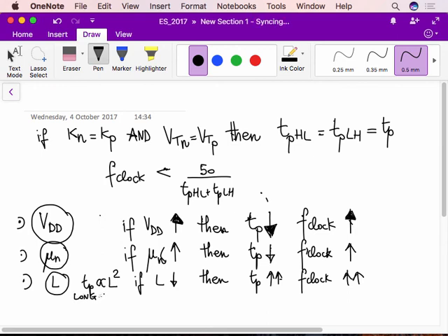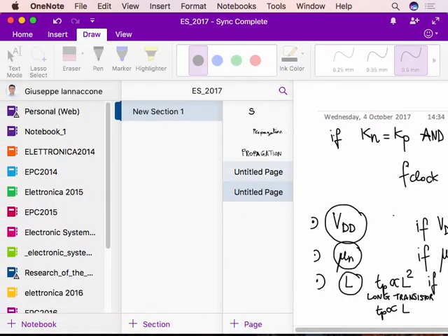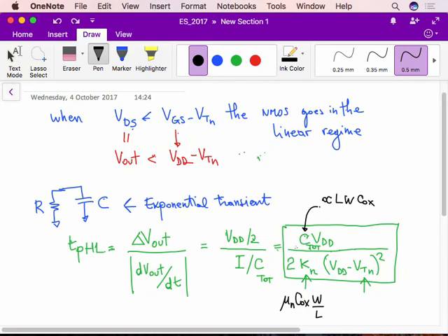So the situation is not so optimistic. For short transistors, actually the denominator does not depend on L. So we have that T_p is simply proportional to L because only the numerator depends on L. Okay. If you remember the expression that we wrote for the current in the case of long transistors, there was no L in the denominator, so there is only a linear dependence on L. Okay?